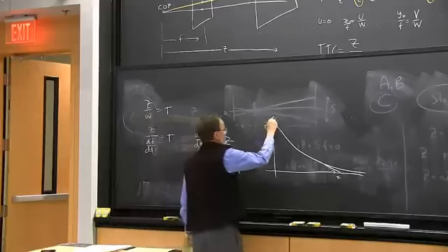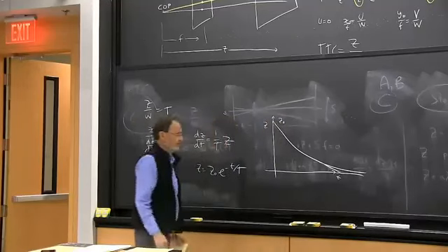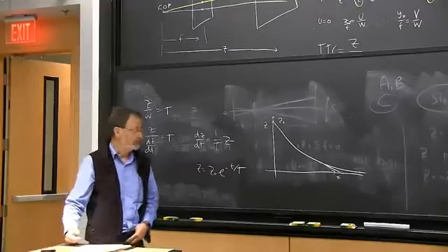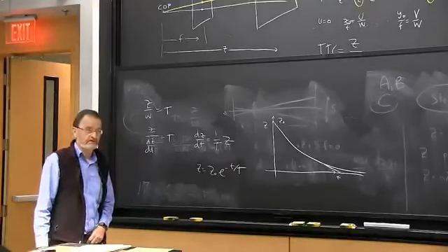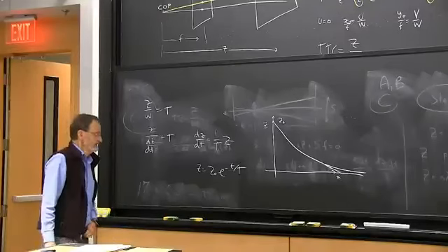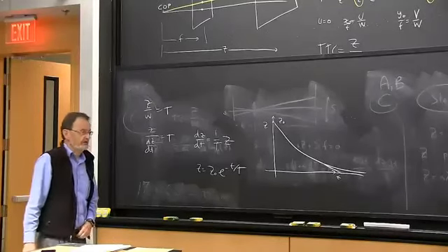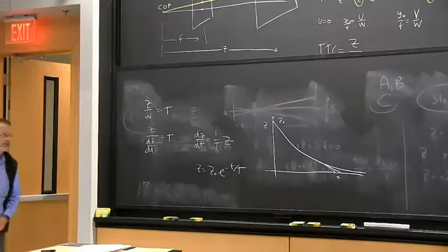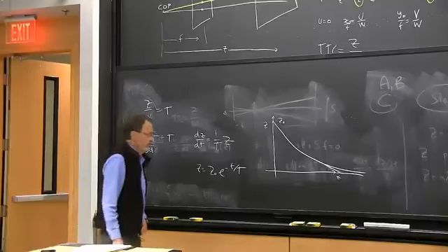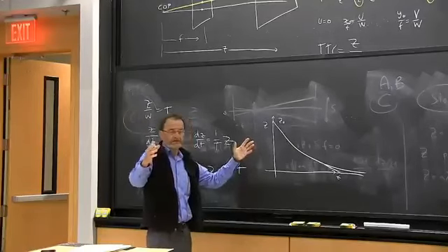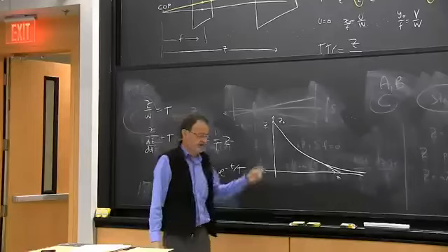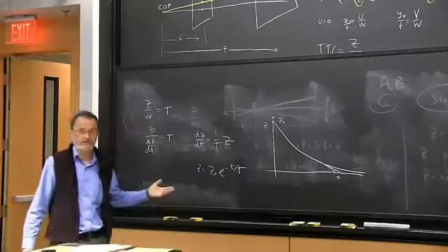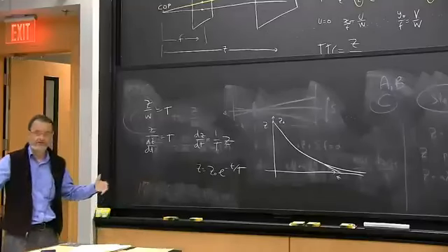So here's our z naught times 0. So it's going to be nice and gradual and smooth, and it will never get there. So that's the downside. So what do you do there? Well, we can do what flies do. They use constant time to contact when landing on the ceiling, and when the legs touch the ceiling, they stop. So we can have wire hanging down from our spacecraft, and when it touches the ground, we shut off the engines, and then it'll just fall those last meter or two.